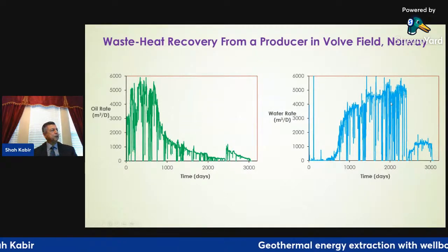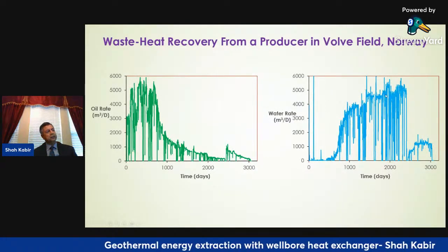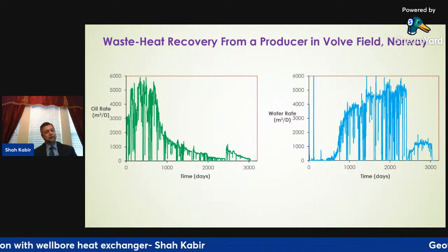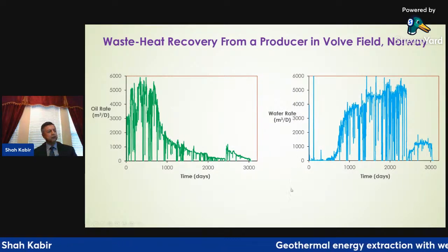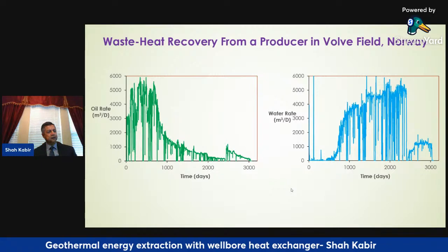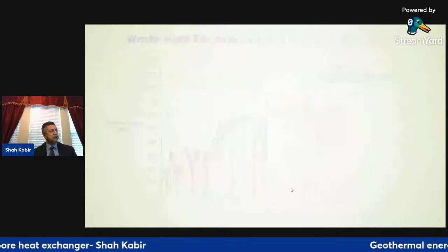But the point here is that because we are producing reservoir fluid, hot water reservoir fluid, relatively speaking, it is bringing in a lot of thermal energy with it. So what we call is the waste heat recovery. So it gives us an opportunity, with a heat exchanger at the wellhead, to harness the thermal energy.